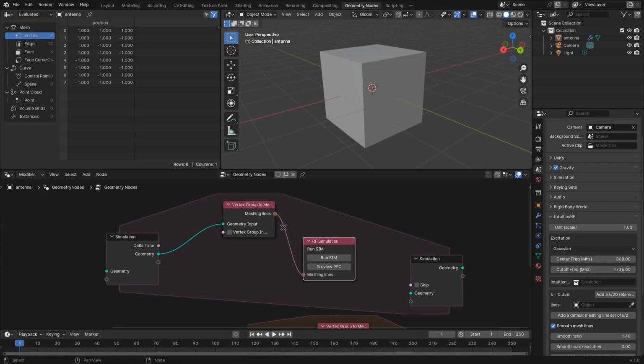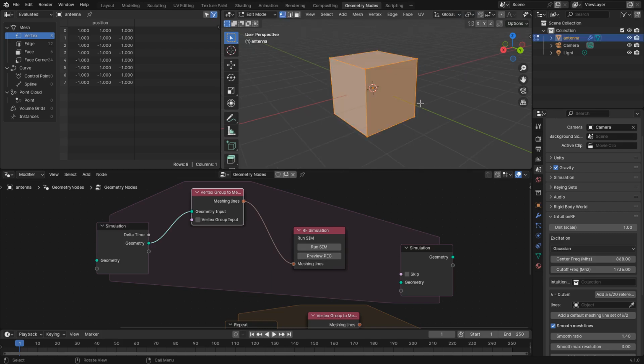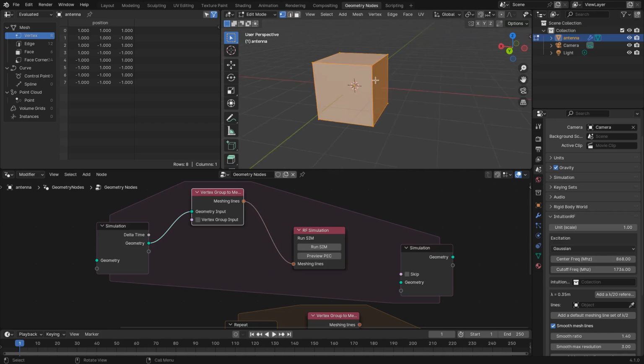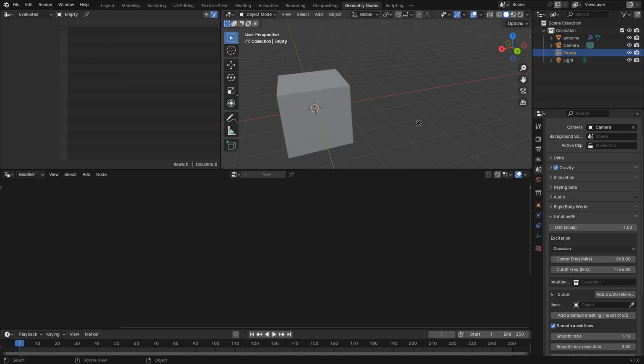So this way you can make it a custom simulation each time and have the outputs piped to whatever you want, and maybe sweep parameters using Blender's geometry nodes, both geometry creation abilities and also maybe model a geometry the classic way and then bind it to new hook objects and move around the vertices with the hooks. So that could be an idea.